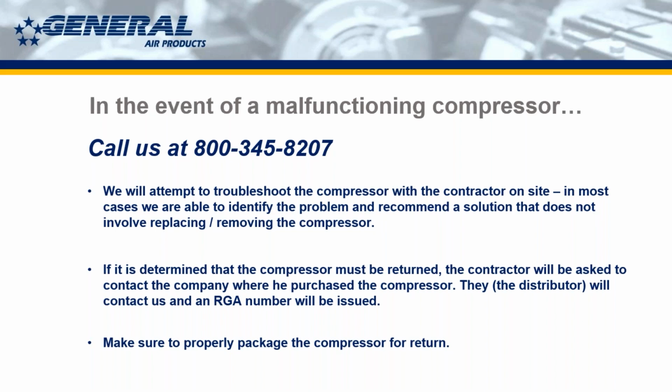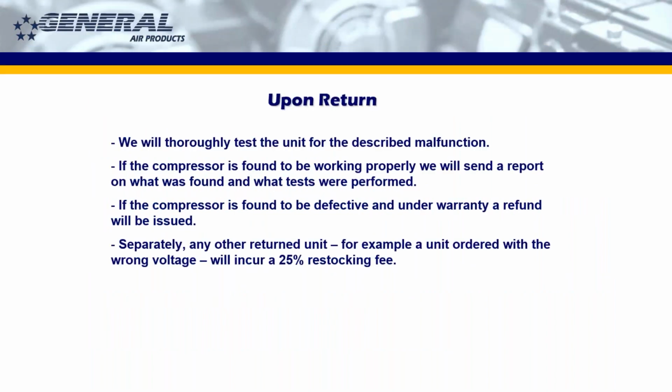So, like I said, following these things in a difficult time, and I understand that it's difficult, will result in a better, faster solution where possible. So following these steps and everything. Yes. So upon return, we test the unit for the described malfunction. If the compressor is working properly, we'll send a report on what was found so that you guys can figure out what was going on there. One of my favorite examples of that is short cycling, and we can sit there and say, okay, yeah, this was short cycling. You have a leak somewhere, so you need to fix that leak before you put anything else in.